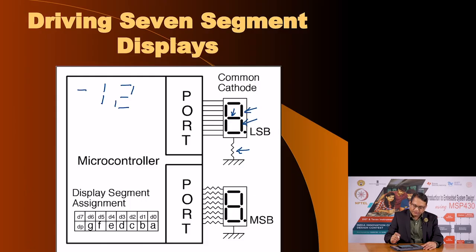Also important to know is which segment is connected to which pin of the port, because in the software this will be used so that you can display numbers or any other symbols on these displays, and we will cover that when we do an exercise to control 7 segment displays using MSP430. Right now we are only looking at the electrical aspects, the circuit aspects of controlling 7 segment displays.